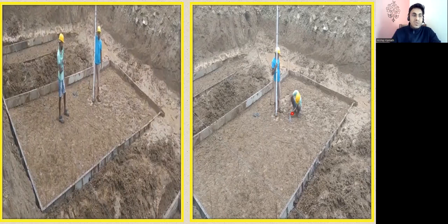The second way is that you have to mark this 75 mm somewhere, let us say I'm marking it here. So this level is my 75 mm. Once you mark it here, if you don't have a total station, we use something called a water tube. Water tube means a tube filled with water, and through that you can transfer the level. Place one end of the tube here, and wherever you want to transfer the level, let us say here, hold the other end of the tube there.